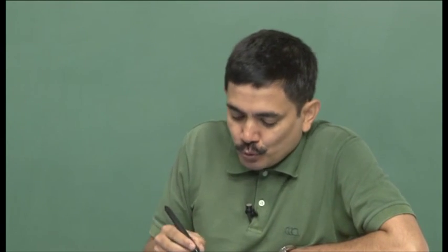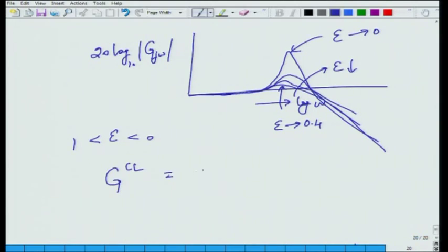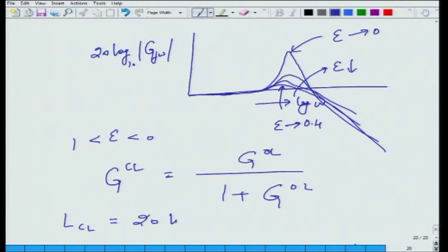So, what that means is, if you have a closed loop system which has a servo transfer function as G open loop over 1 plus G open loop, if you take the log modulus of this guy, which means closed loop log modulus is equal to 20 log on base 10 of G closed loop. If you plot this log modulus, if this guy is showing a large hump, that means you got too much oscillatoriness. This is LCL and this is of course log omega.